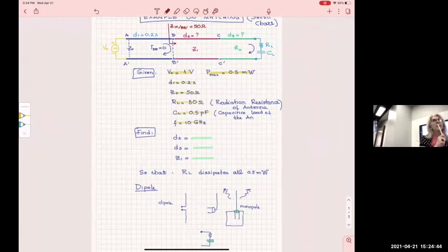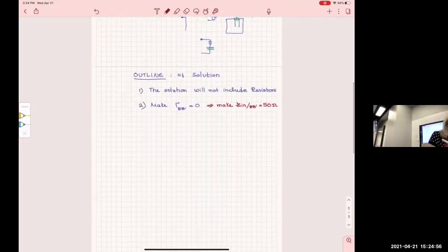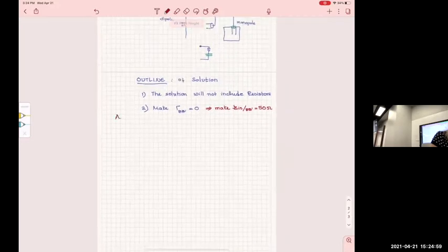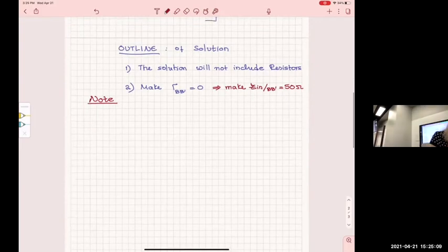Now, what is the other thing that I remember from all of the things that I've seen? I remember the concept of a quarter wavelength transformer. I'll make a note here, because that comes to mind. Since I cannot add stubs, what other things can I have in my toolbox? I have the quarter wavelength transformer. A quarter wave, really we call it for simplicity, transformer,